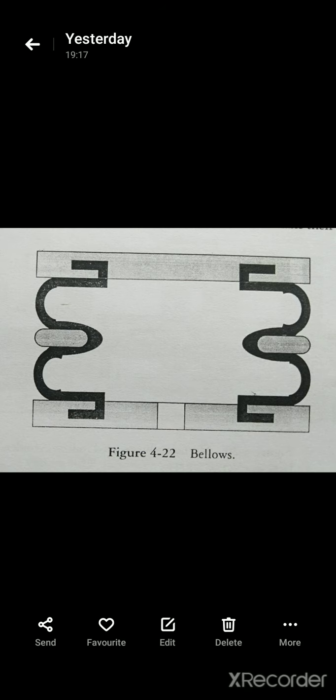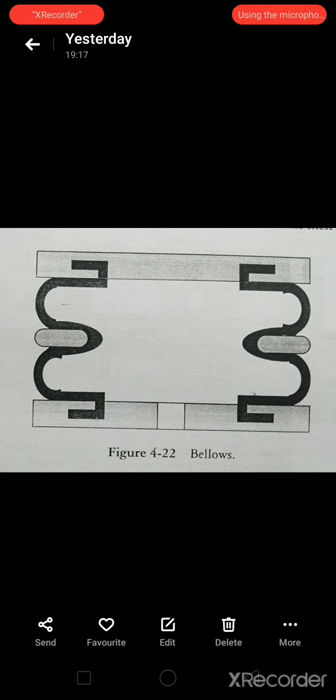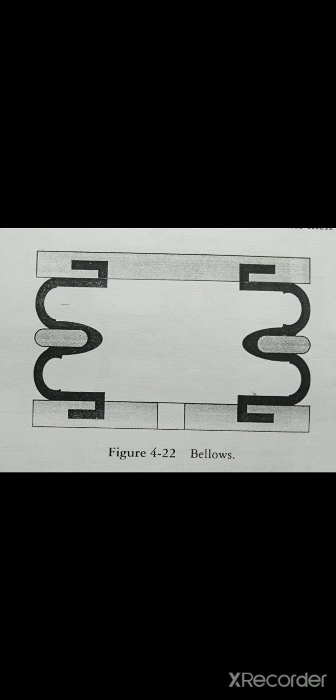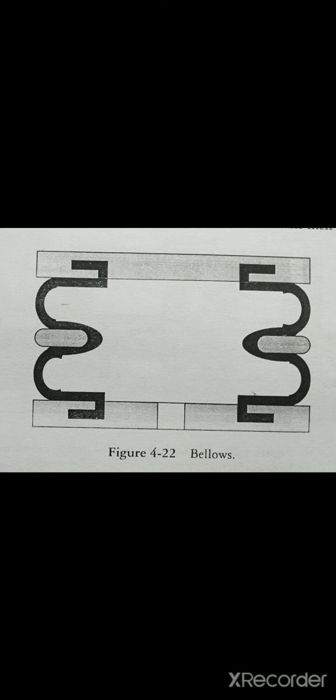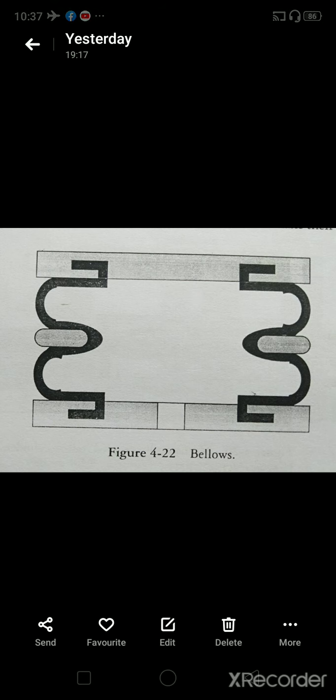A bellows actuator is constructed with a flexible fabric reinforced synthetic rubber or polyurethane or neoprene coated polyamide and reinforced with steel cord or aramide. So when the compressed air is applied to a bellows actuator, it inflates and provides powerful short strokes. This movement can be used to lift a load.